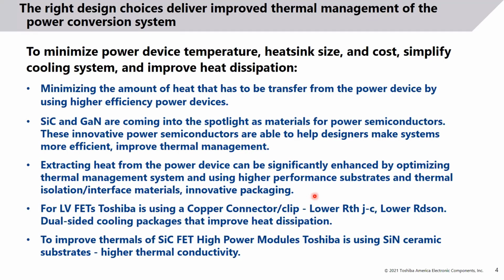For low voltage FETs, Toshiba is using a copper connector clip. It gives us lower RTH junction to case and lower RDS(on). We also use dual side cooling packages that improve heat dissipation.